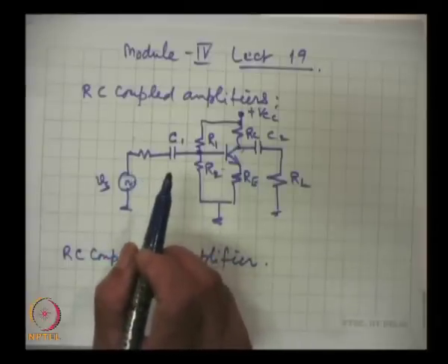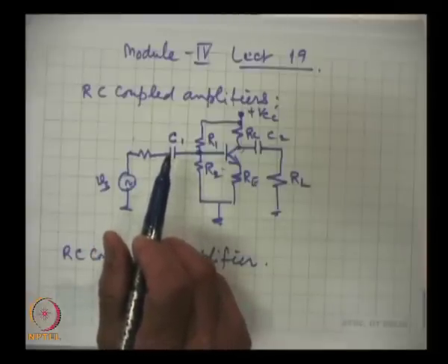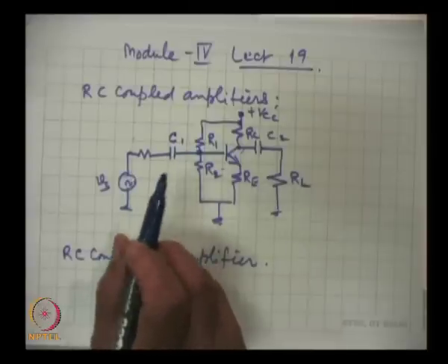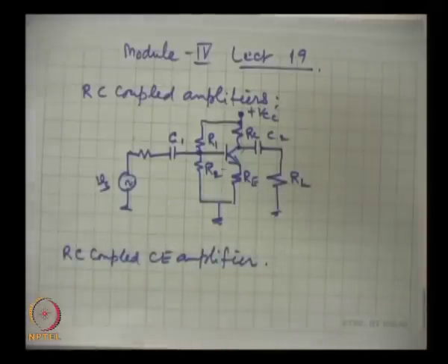This is true for all good oscillators. There is a knob for setting the signal strength you need. Once you fix that, you change the frequency by moving a dial or a knob, or sometimes in steps, but the strength of the signal will not change, only the frequency.